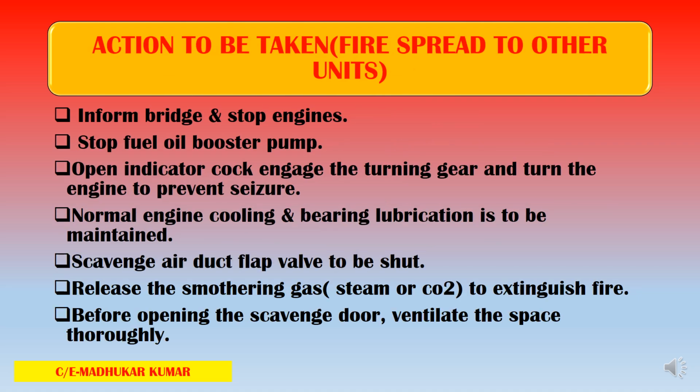Now, the actions to be taken if the fire spreads to other units, meaning from one unit to another. If that happens, it is going to become a larger or major fire in the complete scavenge space. So again, same thing: inform the bridge and stop engines. Now we have to take this action. Stop the fuel oil booster pump, open the indicator cocks, engage the turning gear, and turn the engine to prevent seizure.